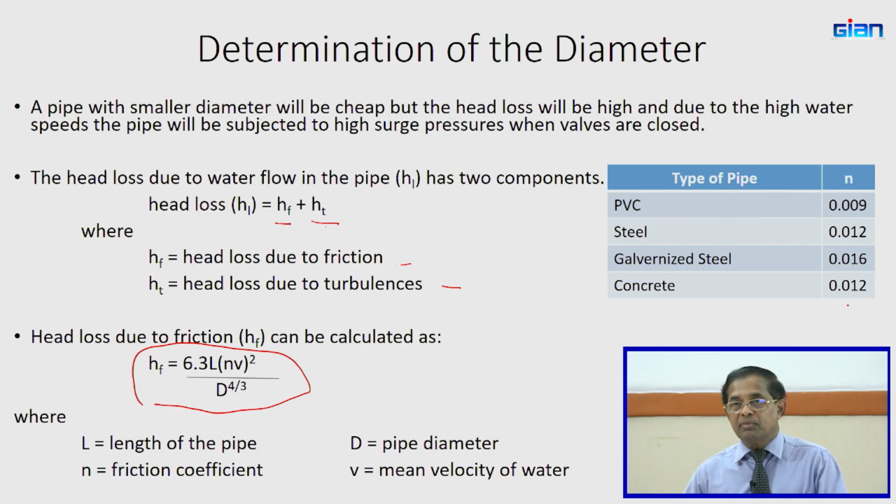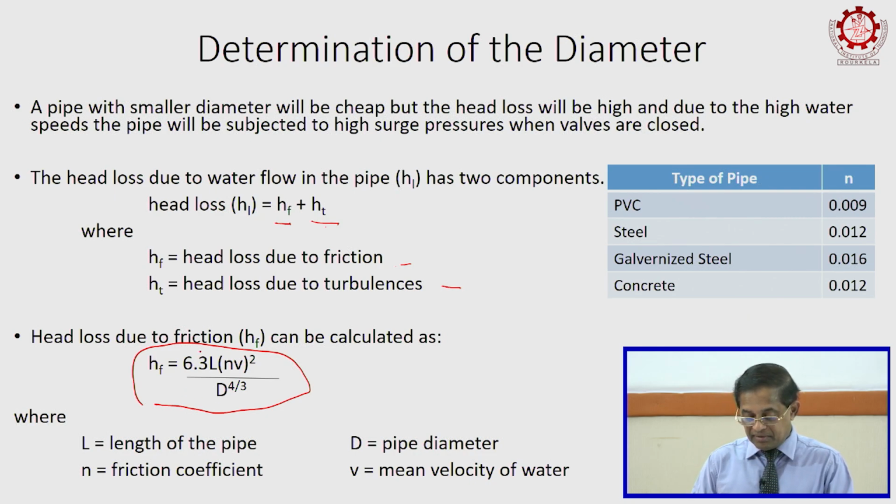Sometimes for very small projects, projects with very small heads, maybe large water volumes but low pressure because of the low head, you can use concrete pipes instead of a steel pipe. So, you can calculate frictional head loss using this. Turbulence head loss we have to calculate separately.